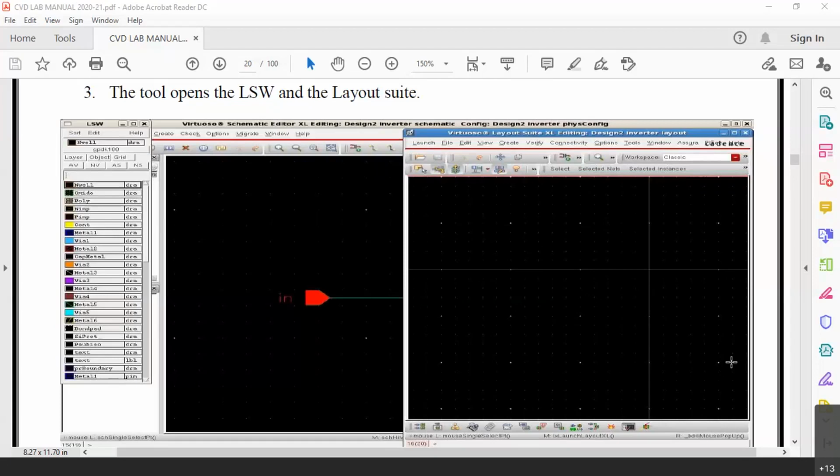So why I am telling that is, whenever we have such a layout file, ultimately it is going to be a database file which will contain graphical data, and graphical data will contain coordinates. Now when the coordinates are important, it is better that we always use the first quadrant here, because in the first quadrant, x-axis is plus, y-axis is plus. Whatever we do, it will be easy for the manufacturer to capture the data from the Gerber file or from the GDSII format. So we will be using the first quadrant only.